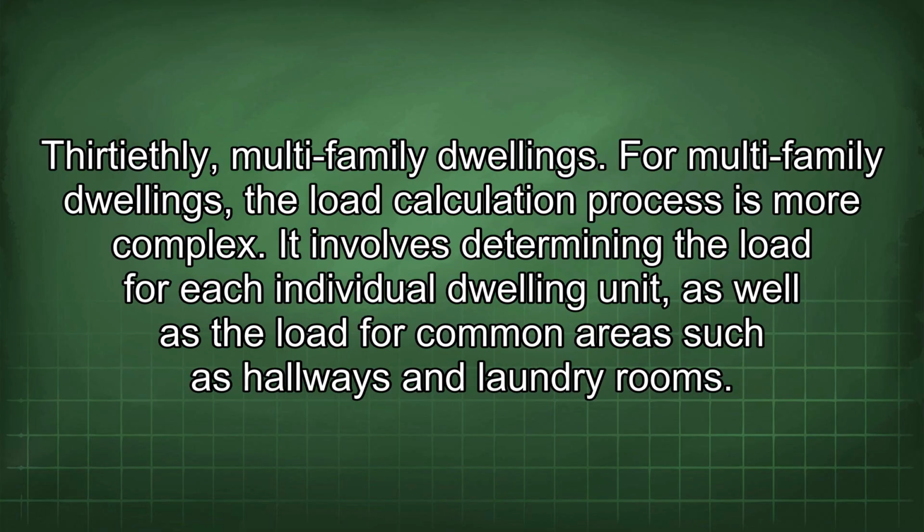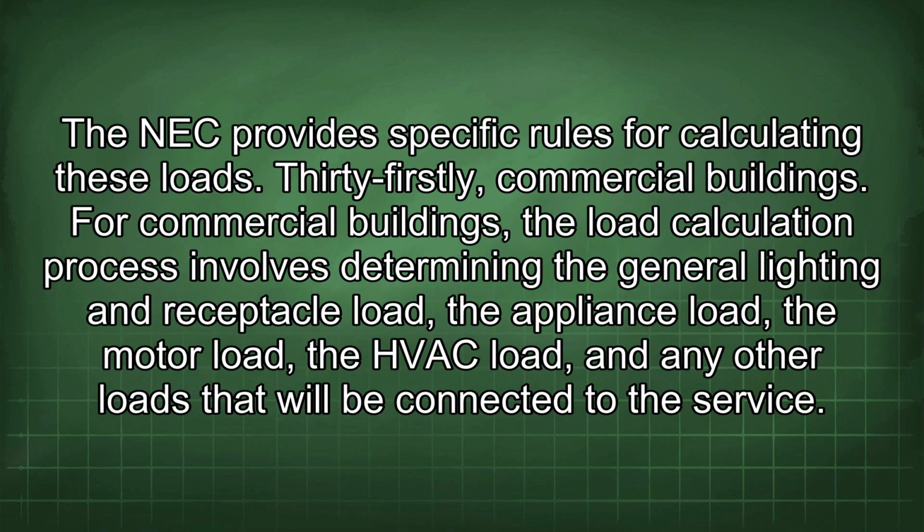30thly, multi-family dwellings. For multi-family dwellings, the load calculation process is more complex. It involves determining the load for each individual dwelling unit, as well as the load for common areas such as hallways and laundry rooms. The NEC provides specific rules for calculating these loads.